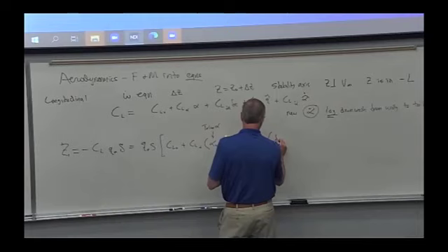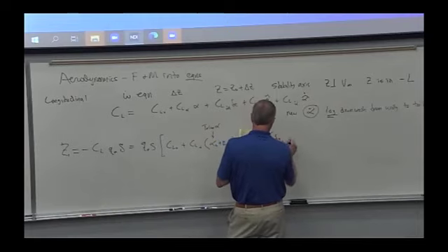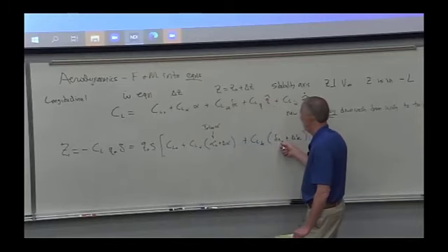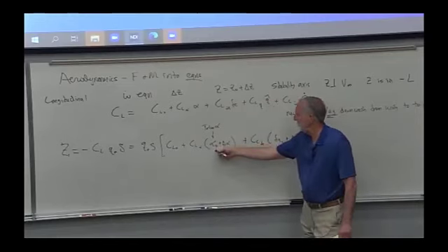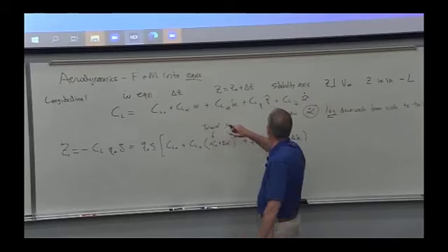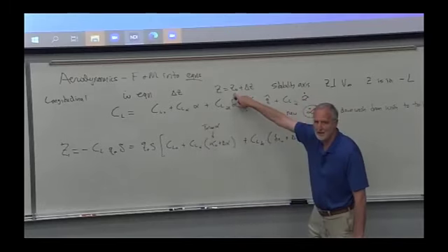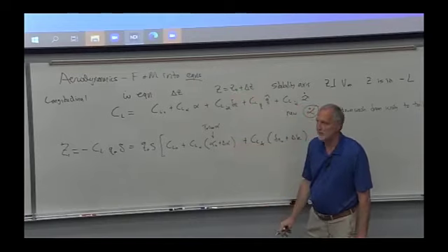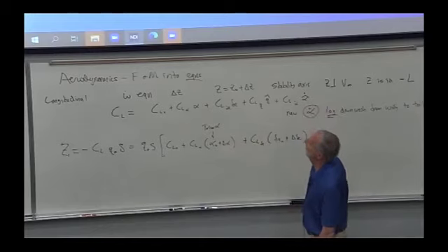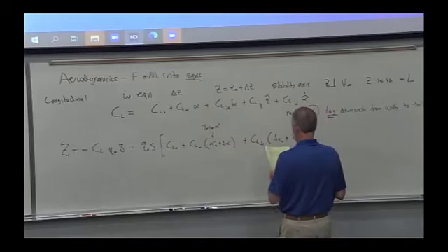And then here's our trim delta E. And notice, instead of putting the word trim there, because I'm shortening it, we just put a 0 in it, because we're talking about the 0 as the steady state. And so the steady state is our trim condition, but instead of writing trim there, we're just going to write 0. I'm over on this board, right? Yeah, good.